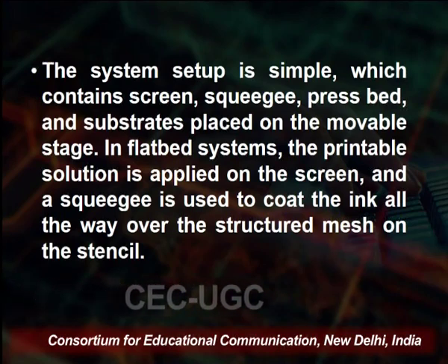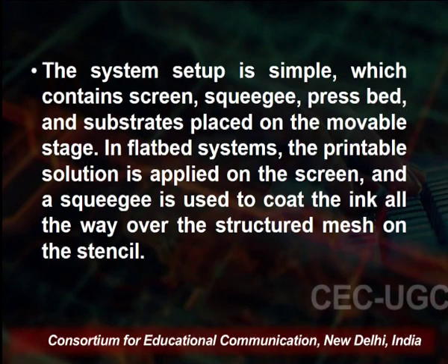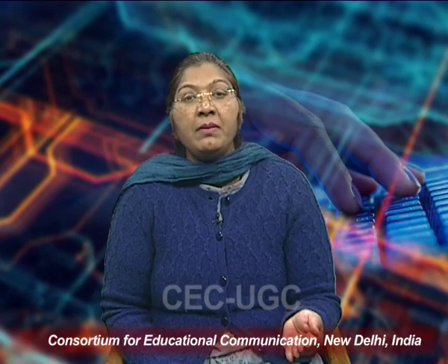So we just flow the ink on that stencil, and we can get the equal pattern through that ink on the substrate. A controlled pressure ensures the dispersion of the ink throughout the holes in the mesh, and the squeegee recollects the extra ink for consequent layers, so that a flat, systematic pattern we can get on the substrate.